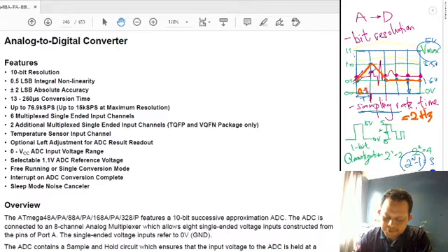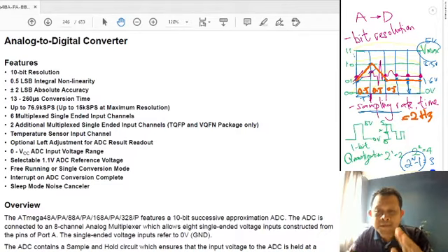The t is 0.5, and then 0.5, and then 0.5, and so on. So the specification of this system is 2 bits with a sampling rate of 2 hertz. When you do the plotting, you will not get the actual signal back, right? So this system is wrong. It does not fulfill the requirements to capture an ECG signal, right?